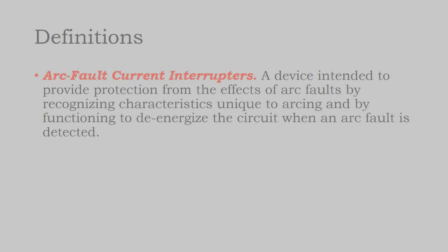And in a solar array, where that kind of fault might occur is in the module to module connectors. What they're called are MC4 connectors. So let me pull this up. MC4 connector.